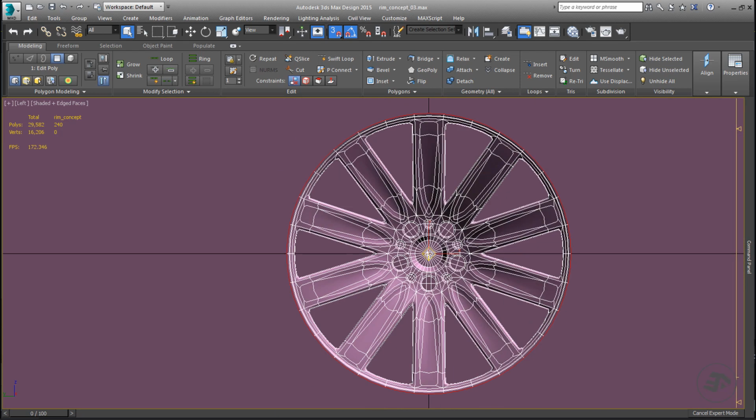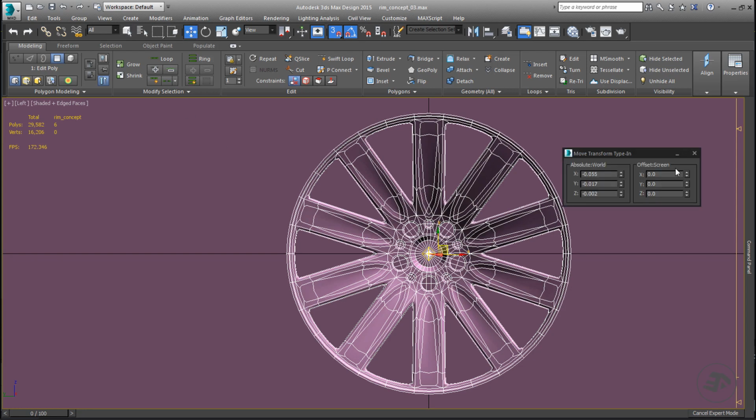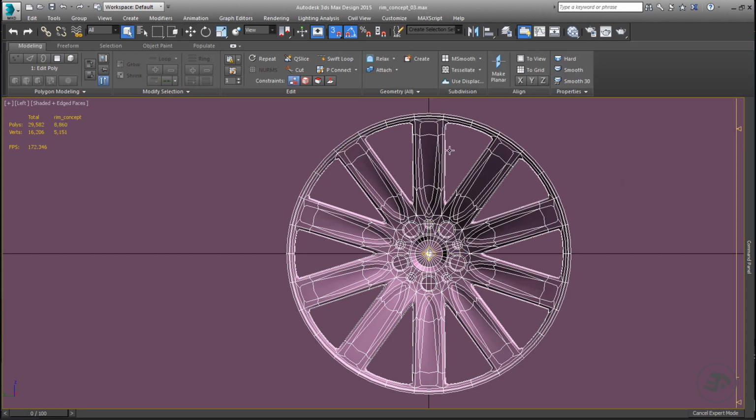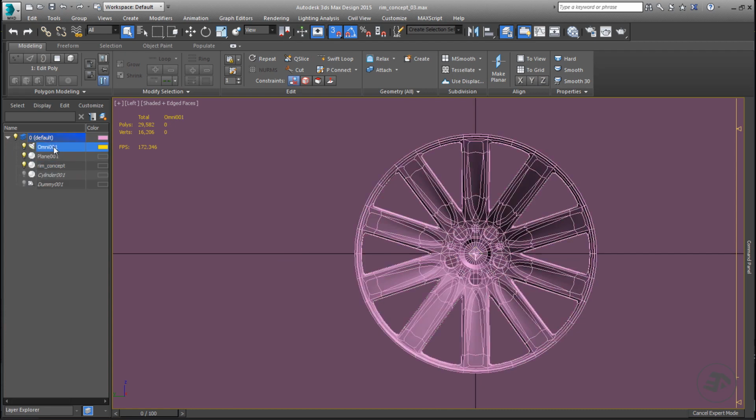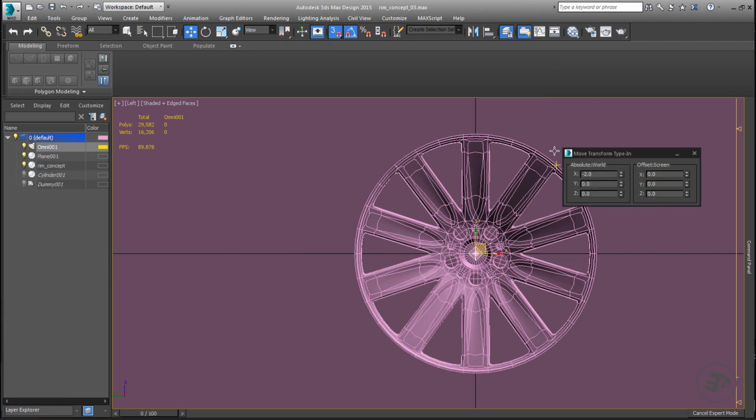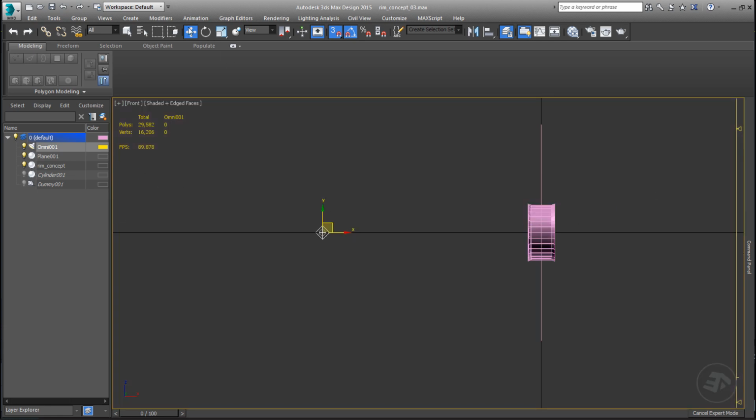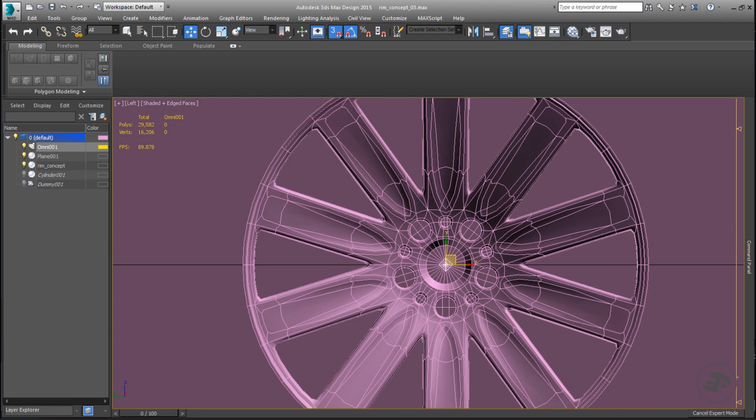The second reason is the light settings. Let's bring the Omni light closer to the rim. Set the light location to be at -40 cm on the x-axis. Let's do a quick rendering.